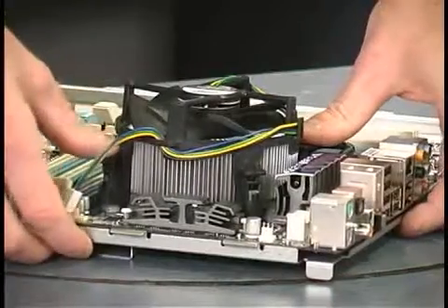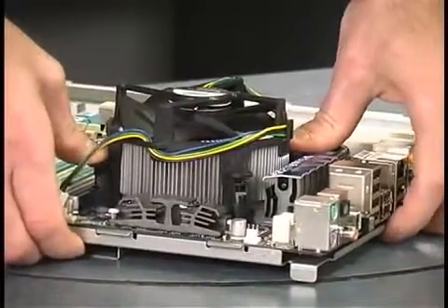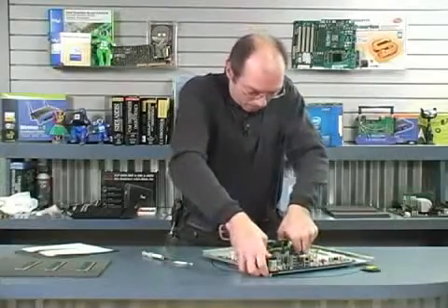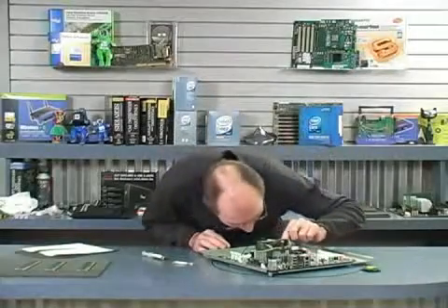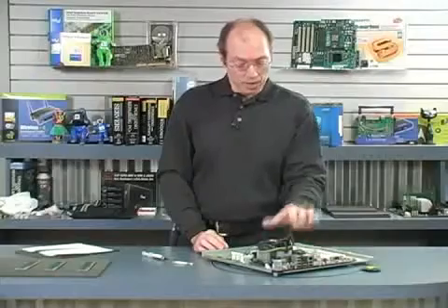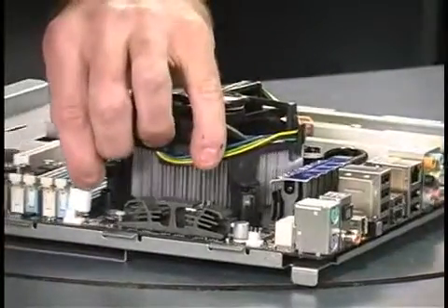I like to do it on opposite corners. You basically push down until you hear them click into place. And then I'll do these 2 corners until they lock into place. Then take a look around, make sure that all of them look the same and that they're all fully seated. These are. Now, once the heatsink is installed, you want to connect the fan, which is right here,